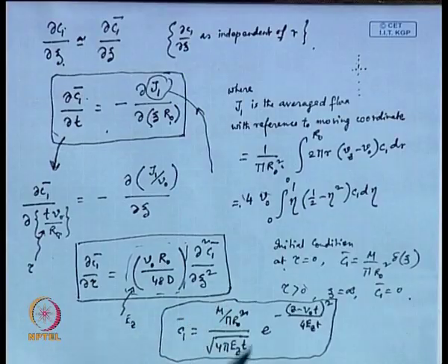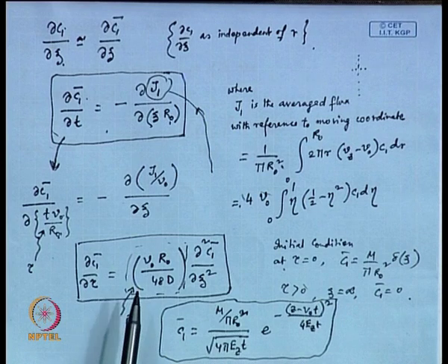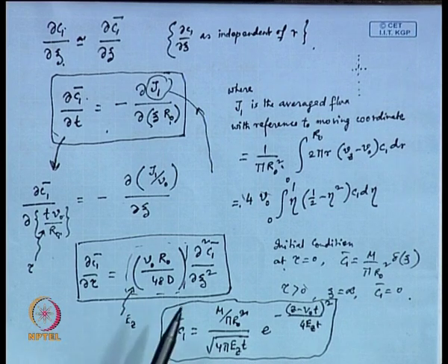Now, we have talked about this circular cross section, that means we talked about a circular capillary. Now, if you do not have a circular one, instead if you have flow between two parallel plates, then in that case this 48 would be replaced by 210. I mean, people have already done this analysis.